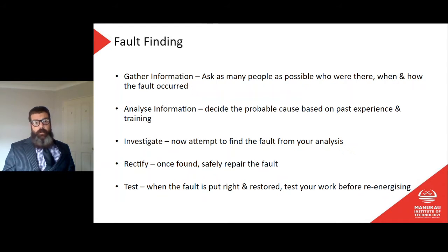I go, well, I'm going to go and check that light then. And I look inside the pump and I go, oh yeah, that light's burnt out. I rectify it, and then I test. And remember, we must test before we put anything back together. We test it for safety. Follow all of the required safety tests before we put power back onto anything.